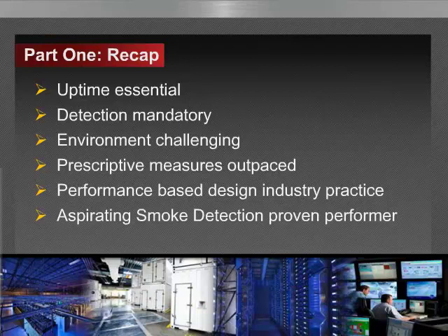Examples of specific guidelines for the use of performance-based design and risk management concepts are addressed in codes and standards such as NFPA 75, the standard for protection of electronic computer data processing equipment, and NFPA 76, recommended practice for the fire protection of telecommunication facilities, BS 6266, which is the code of practice for fire protection for electronic equipment installation, and Australia New Zealand 4360 risk management standard, and of course the SFPE Handbook of Fire Protection Engineering.